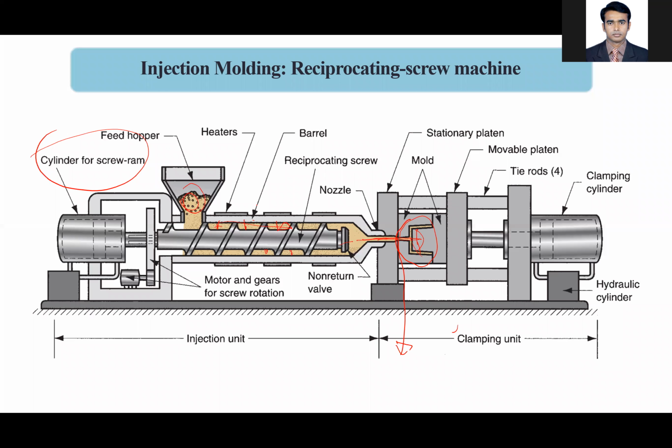There is also another thing we need to remember: how do we remove the air from the material? Even if we compress, air is not going to come out. That is why in some places you need to provide some vents, which are not shown here. And at the same time you also need to provide vents in the die. I'll come to that later. Now, do you have any other question? Anybody else?